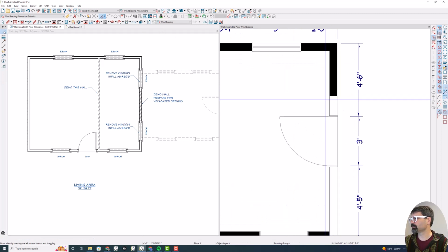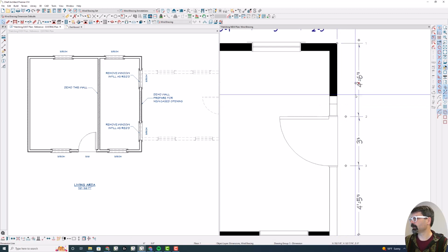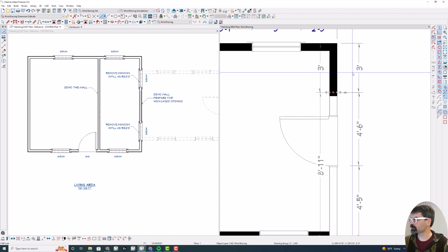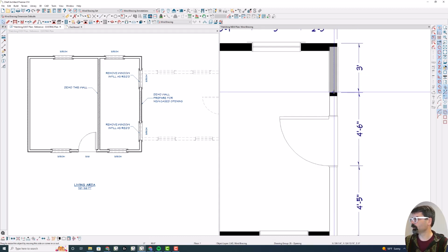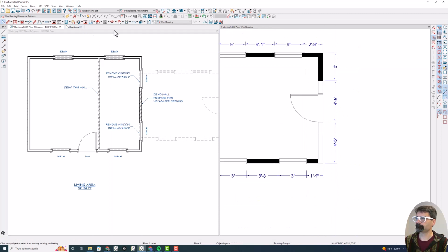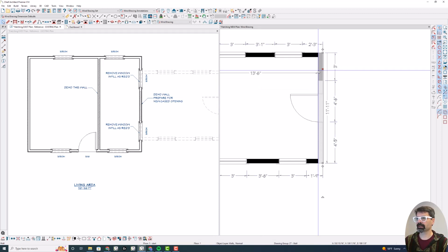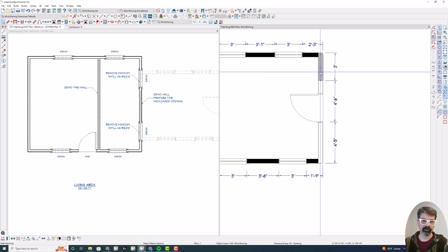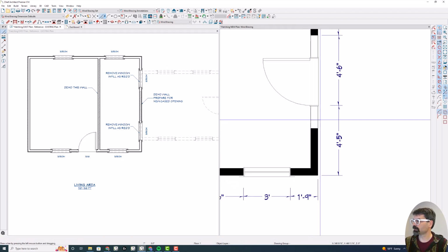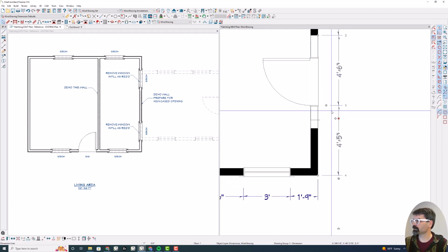Okay, so from here, I'm in wind bracing. I'm just going to draw a line and dimension to it and move that to 36 inches. And move my wall hatching back to that. Now, if I'm not in wall hatching mode and I go selecting this, it's going to select the wall first, and I'm just hitting tab on my keyboard to select that. I can copy paste this wall hatching right over here. And let's draw my line again and make sure that that's the 36-inch.